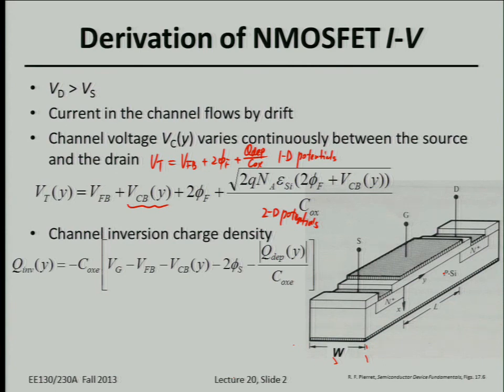And actually that term is the total voltage drop across your gate oxide, right? You always generate some charge to balance the depletion charge as well as the inversion charge in the semiconductor region. So basically that denotes the voltage drop across the gate stack, okay? And once you have non-uniform depletion charge distributions, you have different depletion regions as well as depletion charge along the lateral direction.